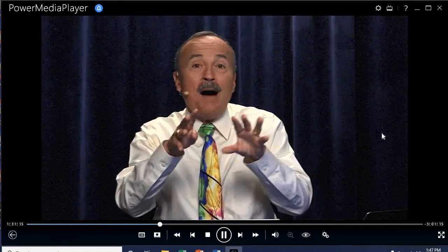But I think our problem is we have a tendency, those of us in the field, that maybe we didn't have that red wire nut, and so we used the yellow one. And then, you know, when you're trying to get it started, okay, I got it. Or it's not all the way in there, you didn't hold it correctly because you're doing it while the whole box is energized, and so you're trying to carefully grab that, you know what I mean? And so these are all things that are wrong things to do.